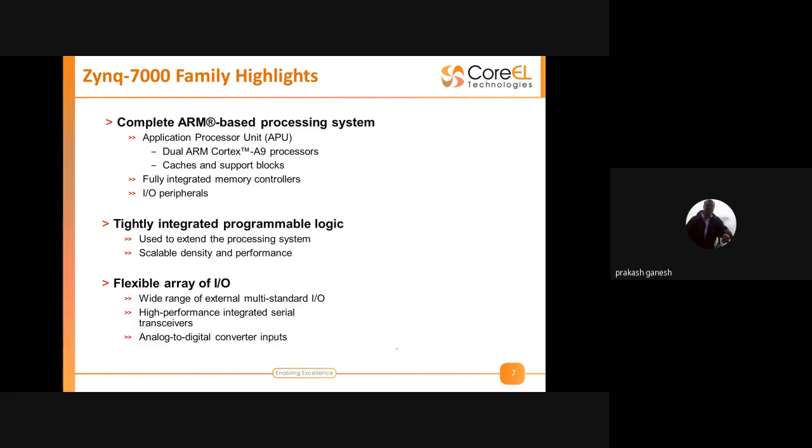Right, and very importantly, FPGAs have flexible arrays of inputs and outputs, because they support different standards: LVCMOS, LVTTL, LVPECL, LVDS, JESDs, and even the SPI-based protocols and I2C-based protocols. Different standards are supported for us. This is no problem for me.